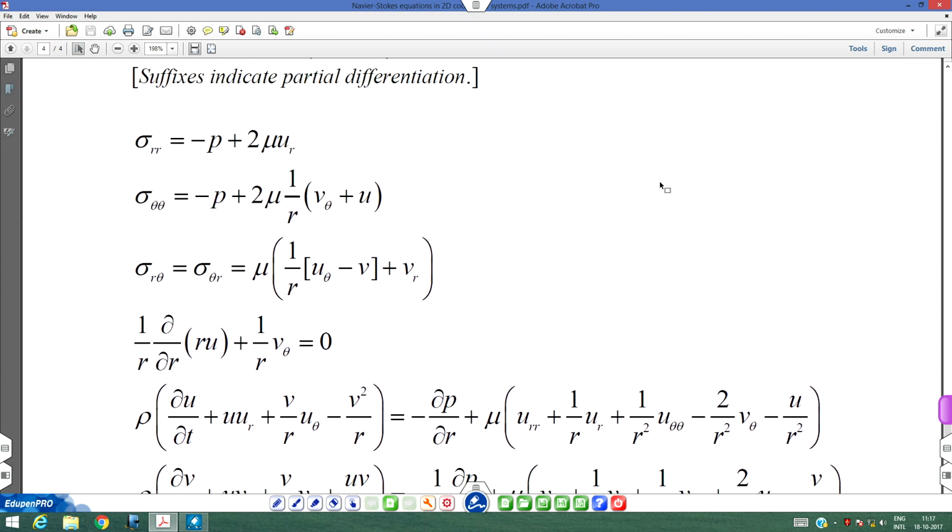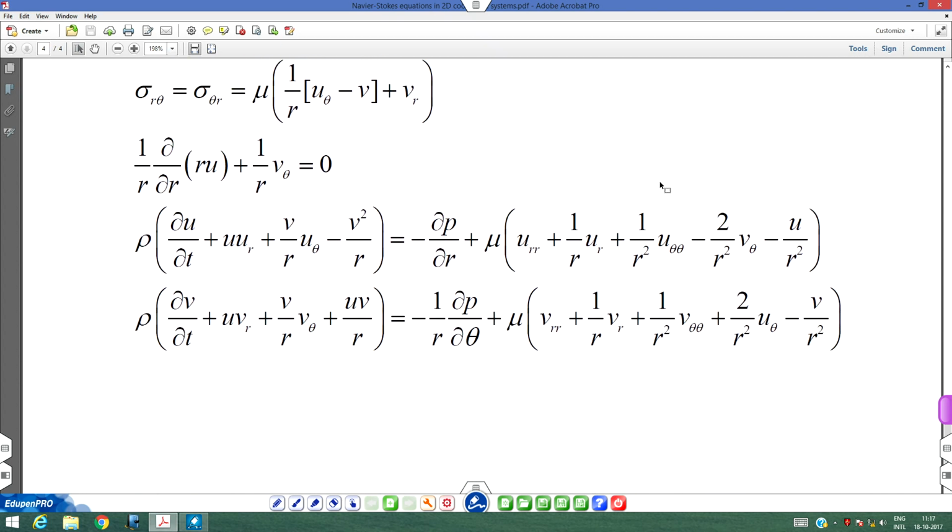Okay. So, in general, what would you do? In general, solve Navier-Stokes equations with boundary conditions. That is where the geometry of the problem comes in. Flow through a tube, flow over a cylinder, that is where you apply boundary conditions and specify the geometry of interest. Once you have velocity distribution and pressure distribution, go back to the constitutive relationship and get the stresses, integrate stresses on the surface of the object or any other portion of the flow field and get the complete force acting on it or complete moment.